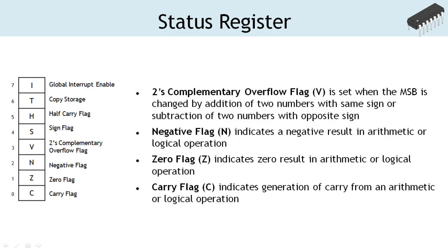Negative flag indicates the arithmetic, logical or bitwise operation has resulted in a negative number. Zero flag indicates the operation has resulted in zero. Carry flag indicates the addition operation has resulted in generation of a carry, or subtraction operation has resulted in a borrow.